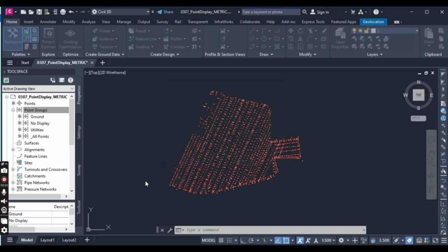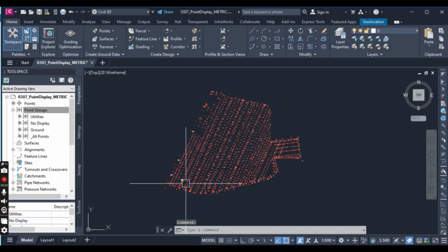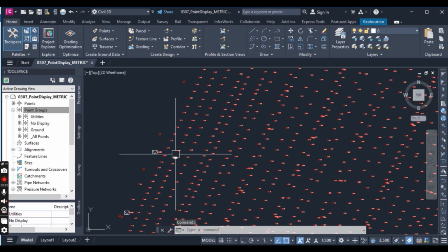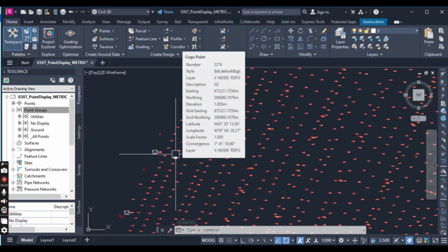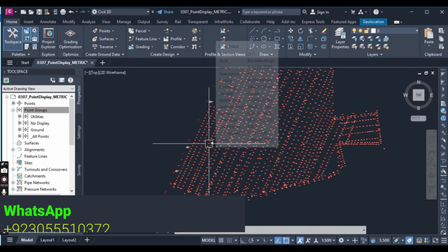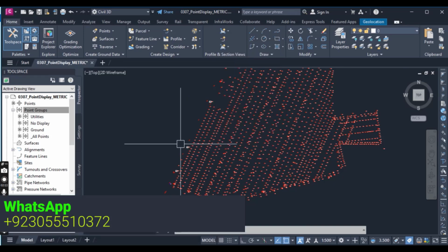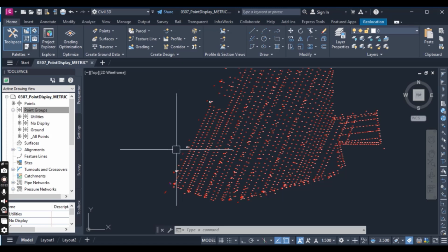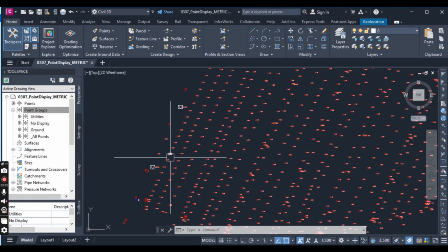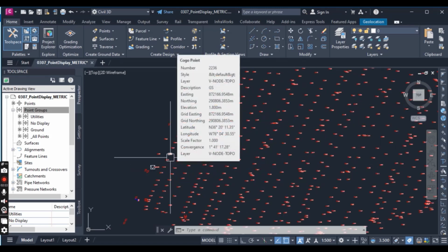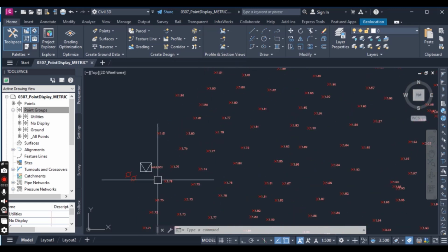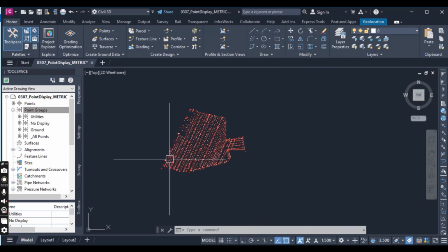Now click OK, and you will see changes with these points. If the display objects are not updated to reflect the change, you can run a regen command. Notice now that only points defined by the utilities group are visible. You can experiment with changing the order of the point groups using the properties.